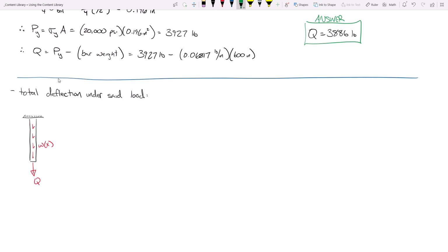See, if I cut a section using a samurai sword or lightsaber, if I'm a sci-fi fan, and here's my section cut, what I'm trying to determine is that normal force as a function of x. Okay? So this dimension, we'll call this x. And I propose that that self-weight that's being applied equals W bar times x. I mean, isn't that what we did up here?